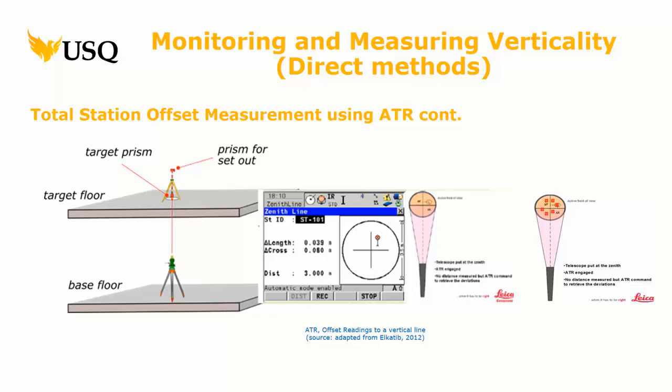What happens if you put a prism bolted to a wall? So it's there, same prism all the time. You start reading to it. Where you're reading, if you get different offsets, that gives you an indication of where you are. So never be scared of going a bit out of left field, right? So this was the preferred method on the Burj Khalifa. It wasn't used on the large German project, right? So there are things, people prefer different things, right?